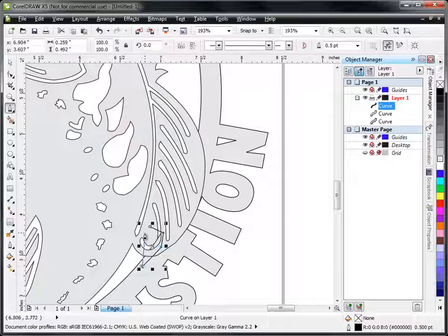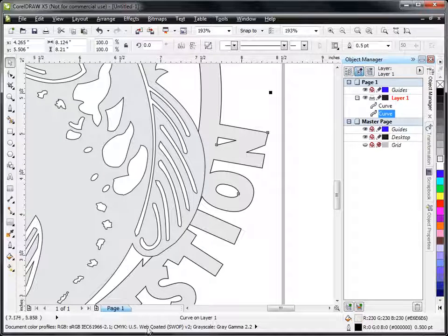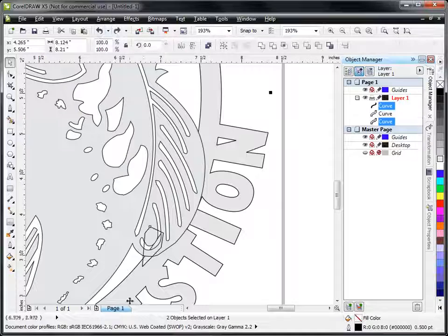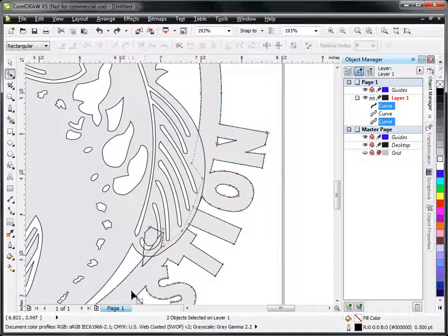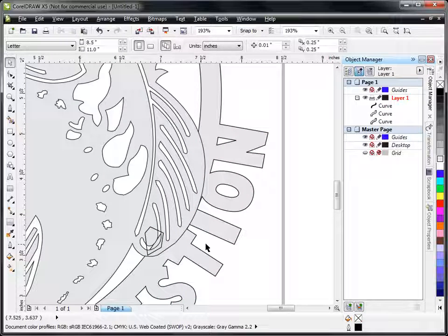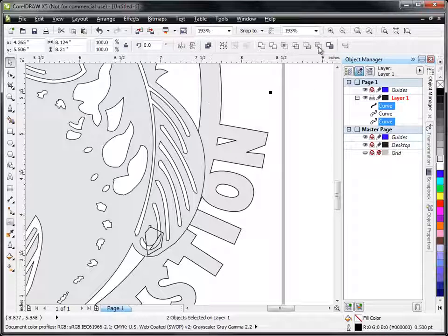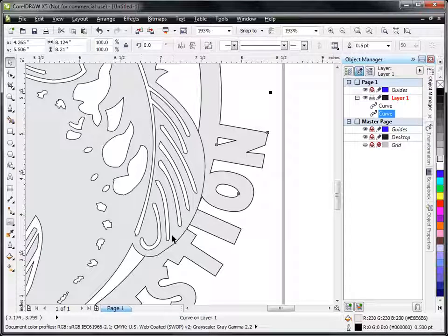I'm going to draw a little piece around this. And this is just a little trick of sometimes things you want to add. Hold down the Shift key, click on the circle, back minus front. Oops, I messed that up. I didn't want that piece to disappear. So let's go over here and take this and move it up to here. And again, we can select our object that we just drew. Hold down the Shift key, click on the circle, back minus front, and you can see now all these fins appear to be in front of the circle.